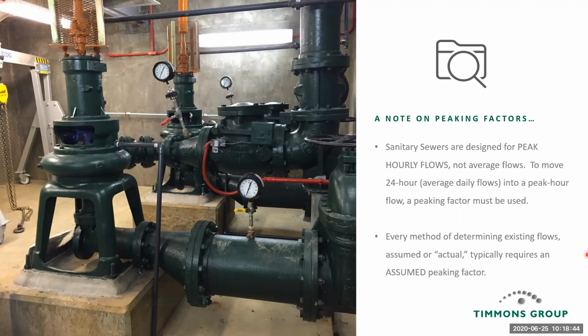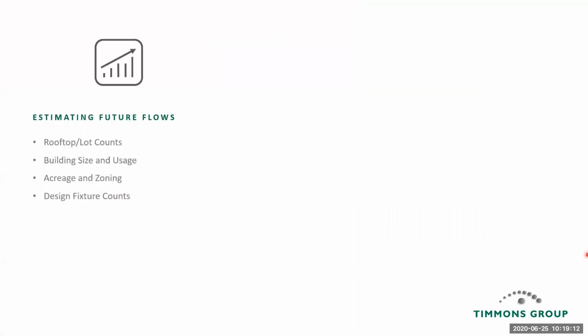It's important to note that just about any method of determining a peaking factor is an assumed method. It's an assumed peaking factor. Even if you have observed data through flow monitoring, and you can look at the peak flow compared to the calculated average flow over that monitoring period, that peak is only good for that monitoring period. It may not be representative of a true peak through the collection system at that location. So I think that's important to note.